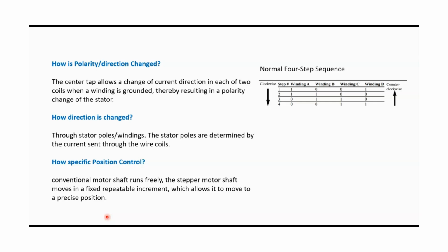Till now we have discussed the direction of rotation of the stepper motor, and the idea behind the stepping is that we apply different pulses at all the windings. So these pulses are changed stepwise. Like here it is a 4-step sequence. There are other types of sequences also which can be applied, and each sequence has a different objective. We will discuss more sequences, but this is a common four-step sequence to rotate the stepper motor.